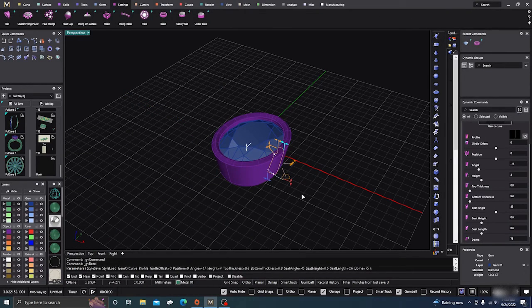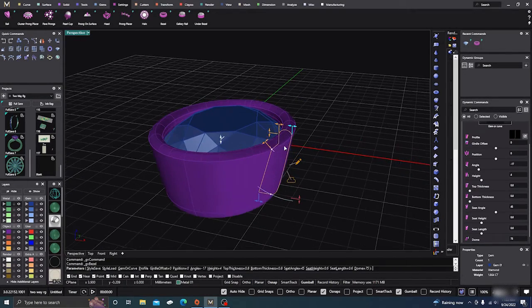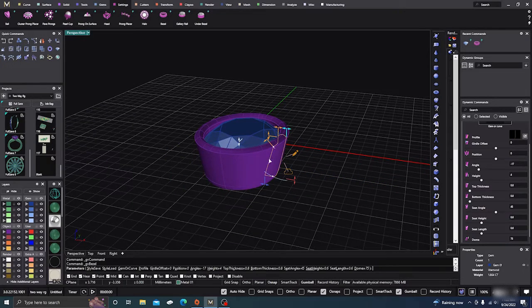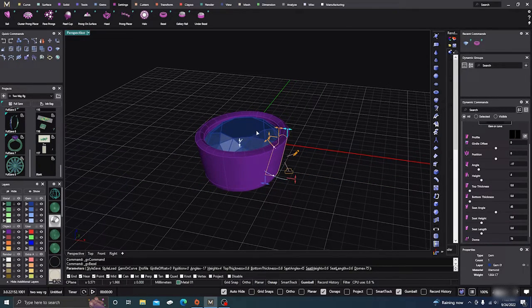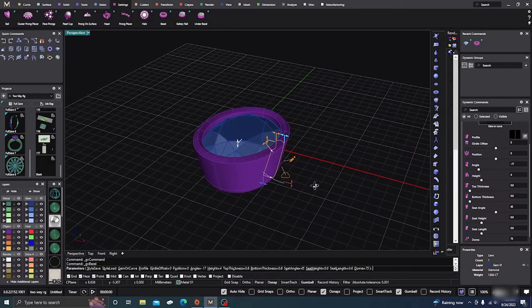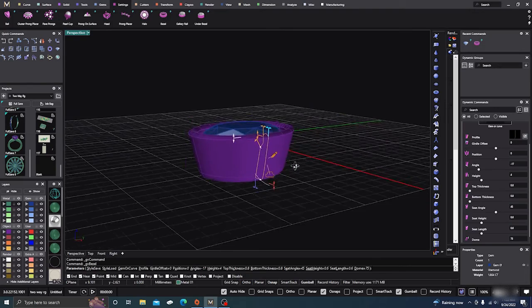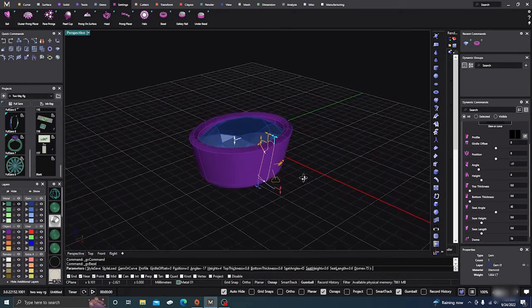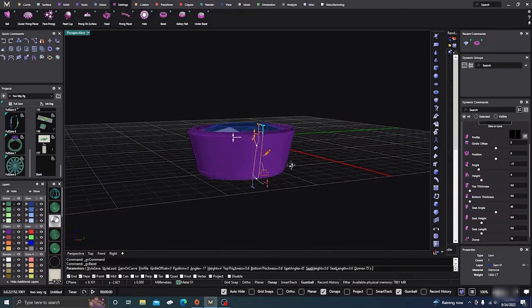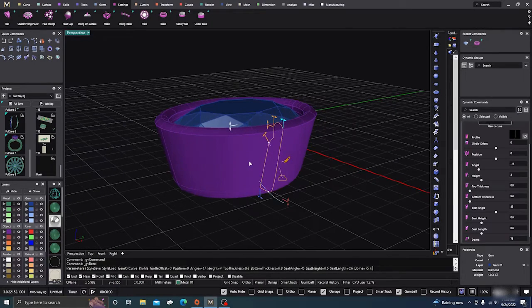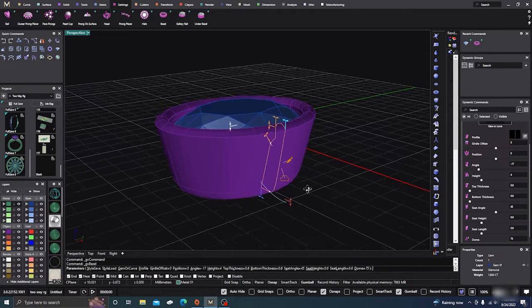Okay, this next section we're going to get into a little bit more detail. It's going to be a little bit more advanced, more time, I guess, so be patient. Right now I have an oval out there. I think it's like a 9mm by 7 by 9 oval. It's a fairly large stone, great for this example, but you could do it with most stones. You have to be cautious though, because on the size of the stone you have to remember the printing process and the casting process need certain dimensions and spaces between things in order to be able to cast efficiently and also to print.